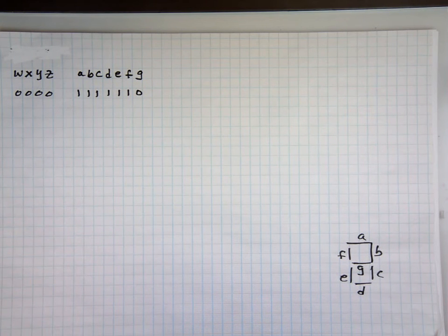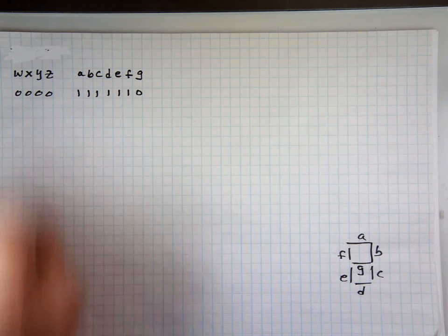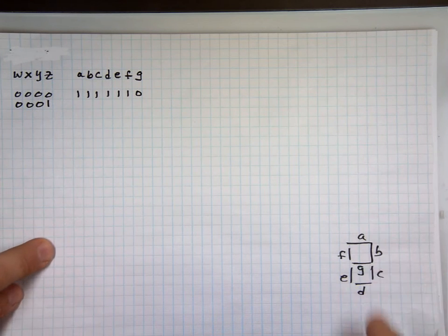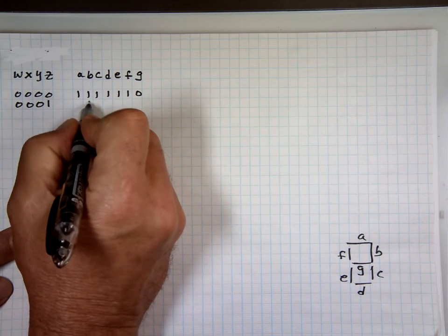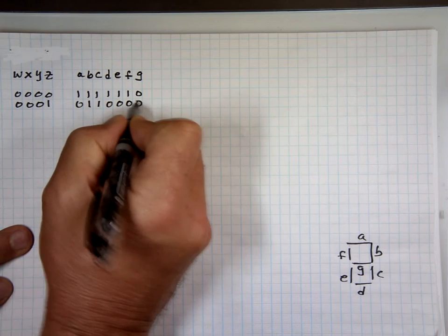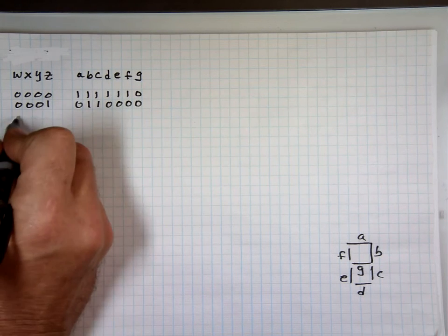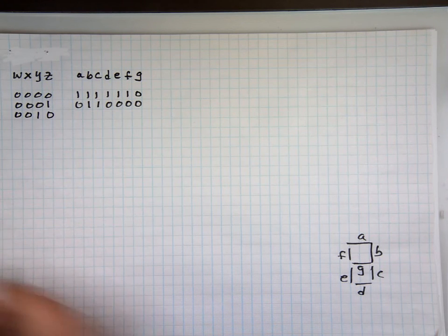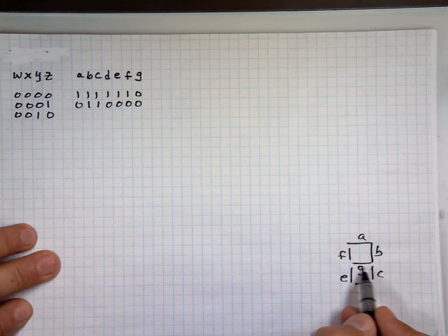When you type in 1, you've got to decide now which edge you want. Do you want this side or this side? You're the designer. B and C. So you want B on and C on, the rest of them are zeros. When you type in 2, I probably want to have A, B, G, E, and D on. F and C, I want them off.